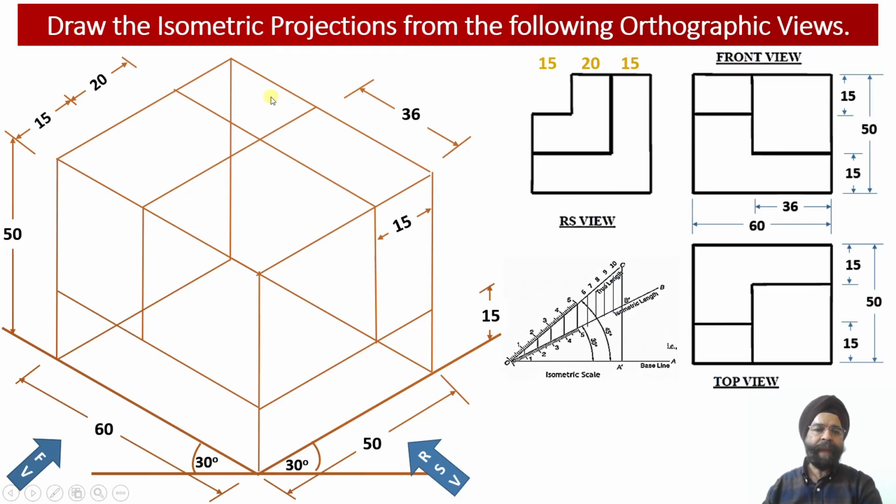So now this web has changed the direction, so that now this web is going to move towards the front side of the solid from the rear side of the solid, and then it is going to move 35 millimeter from the rear side, and then into this 15 millimeter width we are going to have the height of the step equal to 15 millimeter, and again the width of the step will be 15 millimeter. So now we can see over here we have formed the step from this isometric projection line which is going to measure 24 millimeter.